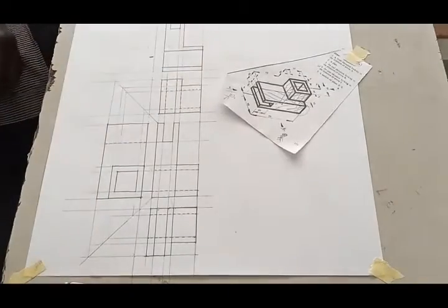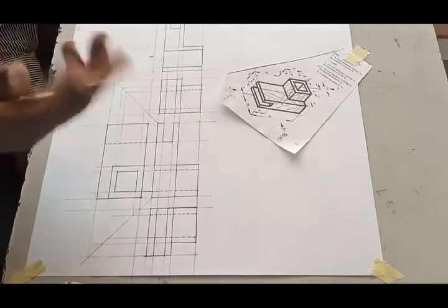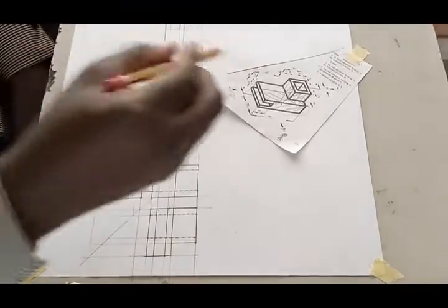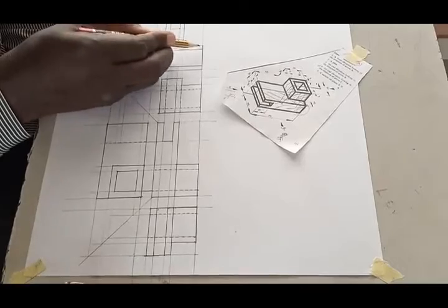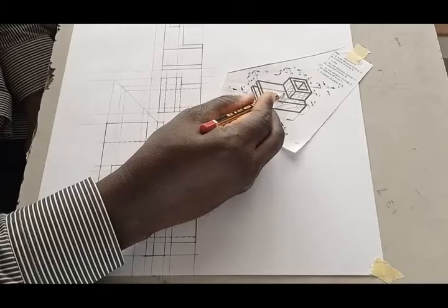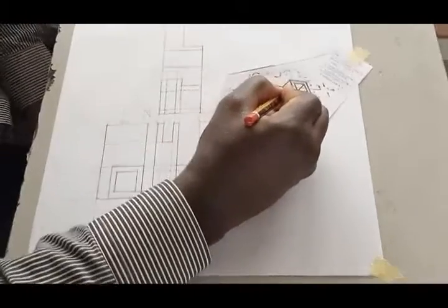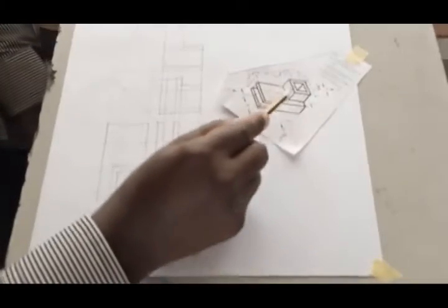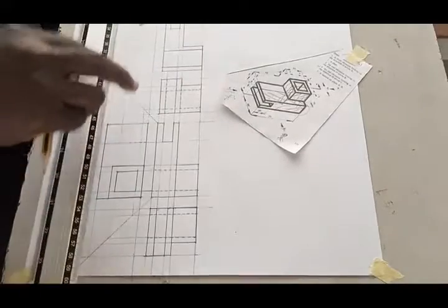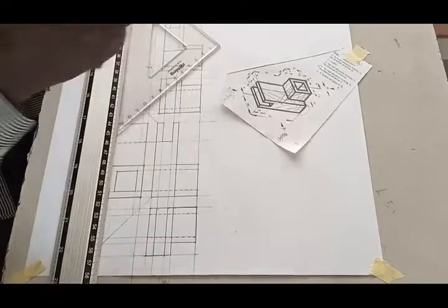Yes. So now, since we have been able to draw this, we are now left with sectioning, to section the portion. So all this portion will be sectioned, because when you are cutting, your material will cut through the thickness of this top, the bottom, this portion here, this portion, it will be hidden line, it will be thick line, it will be shaded line. So you put your section line there, and remember you section with 45 degrees set square.